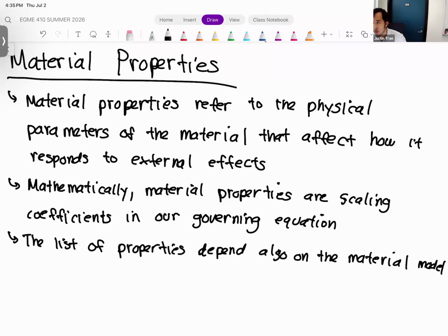Certain materials are loaded by default, and we'll see that in our activity too. If your material is a fairly common one, you can select it from the list within ANSYS itself. But there also are different ways to apply different material models and different material constants, depending on the material that you're working with. Okay, excellent. Thank you.